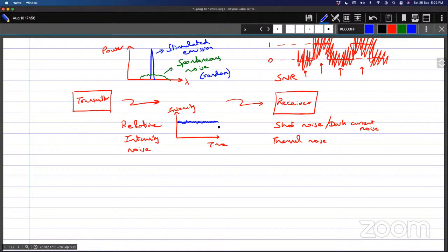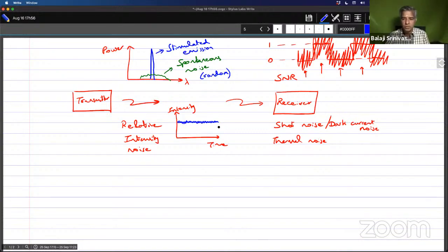Okay, great. All right. And then, of course, there was also this question about, what is phase noise? Now, phase noise corresponds to whenever you are receiving a light wave at the receiver. You are expecting ideally a monochromatic wave, but it's really not a monochromatic wave because there is a finite range of frequencies that are being emitted. So there will be some polychromatic aspect of light. But anyway, that will have a certain phase.